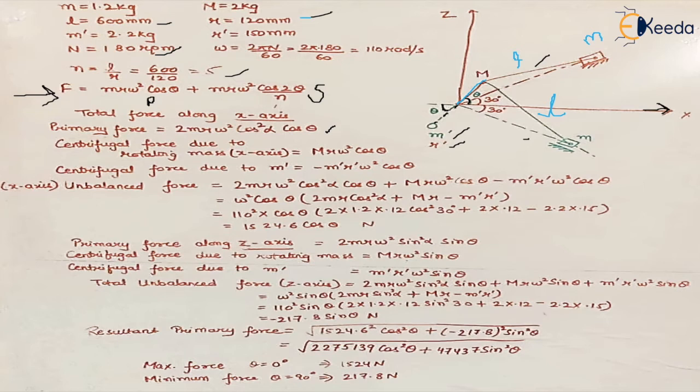So in case of the first cylinder, the angle which the crank makes with the line of stroke is theta minus alpha, which is theta minus 30 degrees, and in the second case it is theta plus alpha. So for both the forces, their x component will be the cos alpha factor, right? So when we add the two forces, we get this equation, and we have already done the derivation in another video.